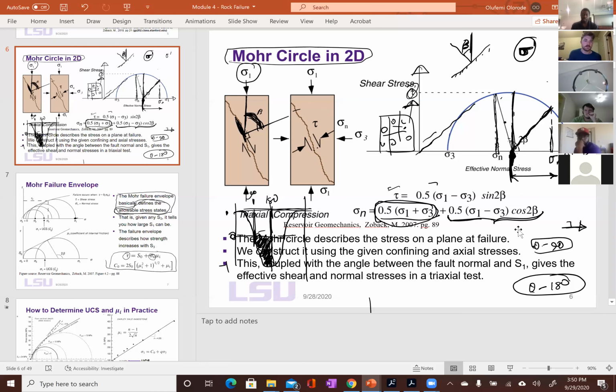That would apply for an intact rock, where you're applying the stress on an intact rock with no pre-existing faults. But if you have pre-existing faults already at an angle, those pre-existing faults were created when there was a different stress regime, right? Which wasn't normal. So yes, if you're trying to create a new fracture in a normal faulting regime, like in a core, it will be at an angle of 60 degrees. But why do we have fractures at other angles? Because the prevailing stress state was not normal at that point.